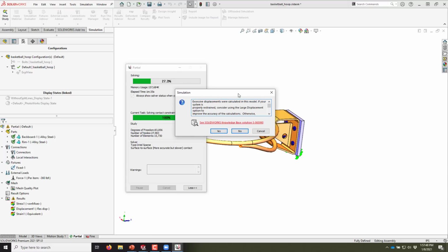Not related to the example at hand, but is there any way in SOLIDWORKS Simulation to dictate element type, for example? No, we don't use quad elements. We don't use hex. They're all tetrahedrons: Tet 4s, Tet 10s for tetrahedrons, and triangles are Tria 4s, Tria 6s. For those of you a little more technical, basically they're triangles and tetrahedrons, and then beams. There are several different types of beam elements in the software. SOLIDWORKS does not support hex elements. Thank you, Eric. You got it.